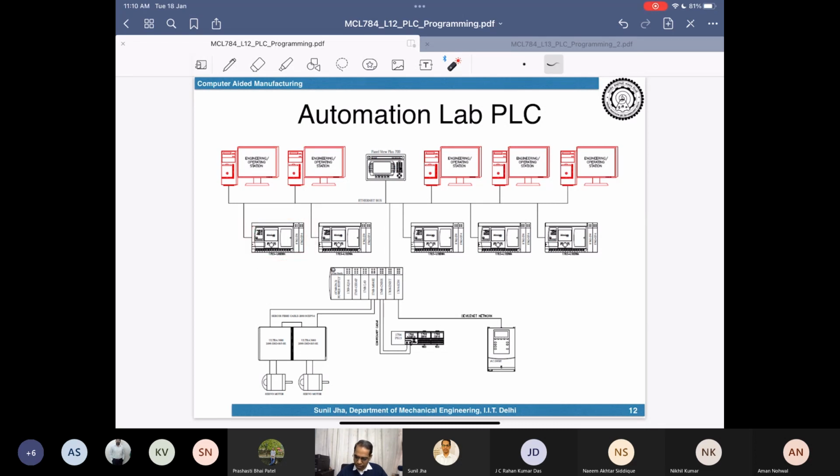We also have this modular PLC, which has additional functionalities and more capability than these standalone compact PLCs, because we are able to control motion, that is servo motion, with the help of CompactLogix. These PLCs may not be able to do the motion control part. So if I am designing a machine where we need to produce a motion, then certainly this will not work. That is how we distinguish them. This kind of system we call a PAC, a programmable automation controller, which gives you more flexibility than just simple logic implementation.